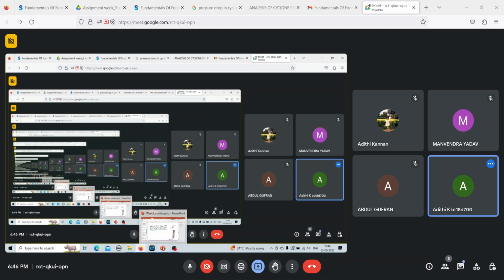But what you need to notice is that there will not be any cake deposition here, or there will be very minimal cake deposition, because you're continuously passing it at a very high velocity. So nothing will get stuck on here. Everything will get passed to the other direction. Whereas if you had passed your slurry in a direction perpendicular to it, you will have small particles being deposited here over time, and you will have something known as a cake deposition. So those are known as cake filters.